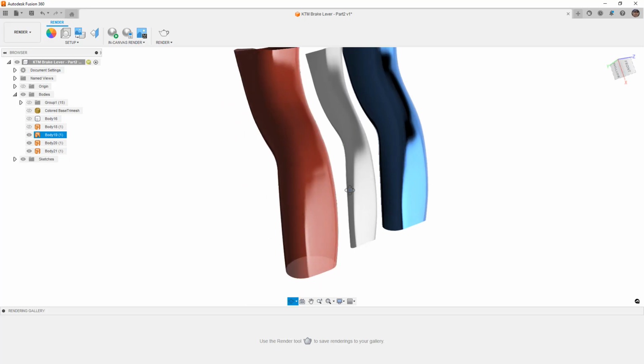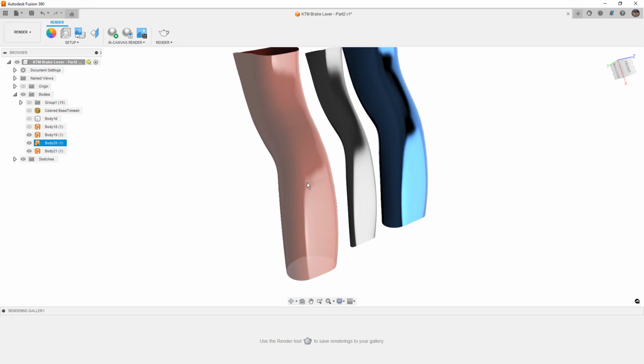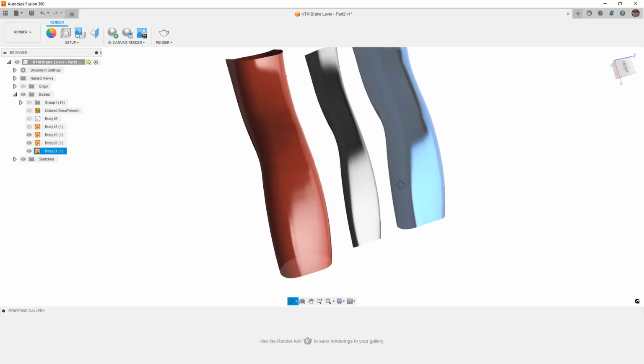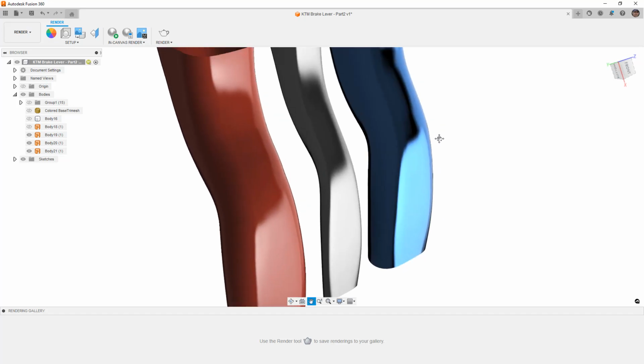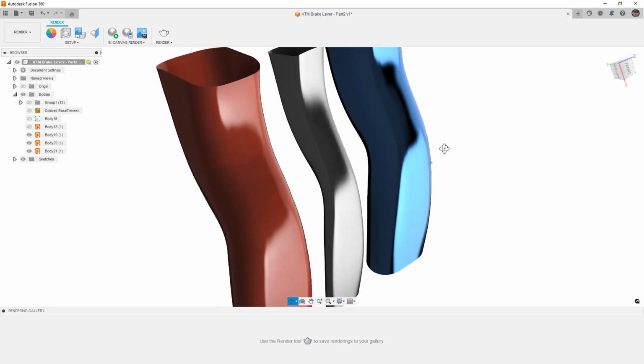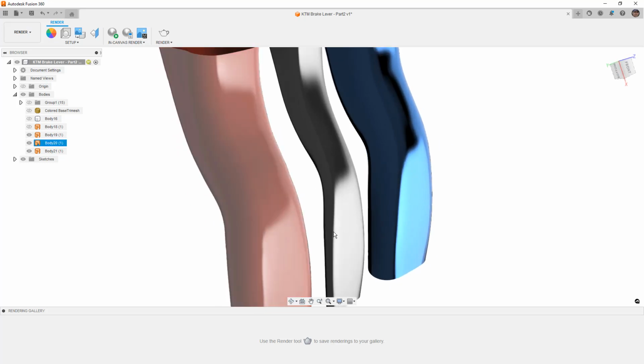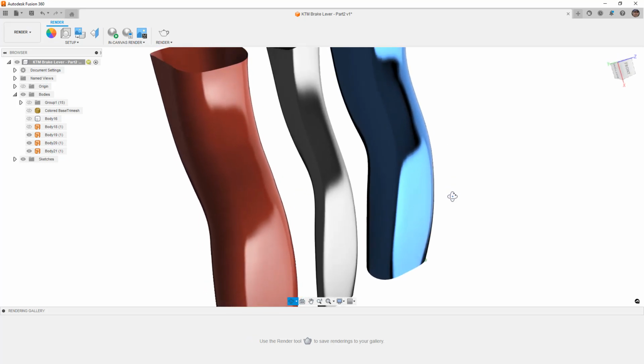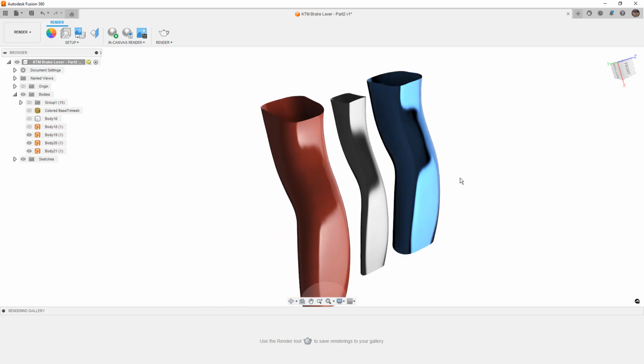You can kind of see there's a little bit of a disjoint that happens right here in this reflection. It sort of gets light and then it gets dark again. And when we take a look at the freeform version of that, we don't get that same sort of ripple in the surface. So we can see a lot of those. And it's not the fault of the surface tool that we're using. It's not the loft tool. It's the curves that we're using from those mesh sections. That's where this problem is coming from.